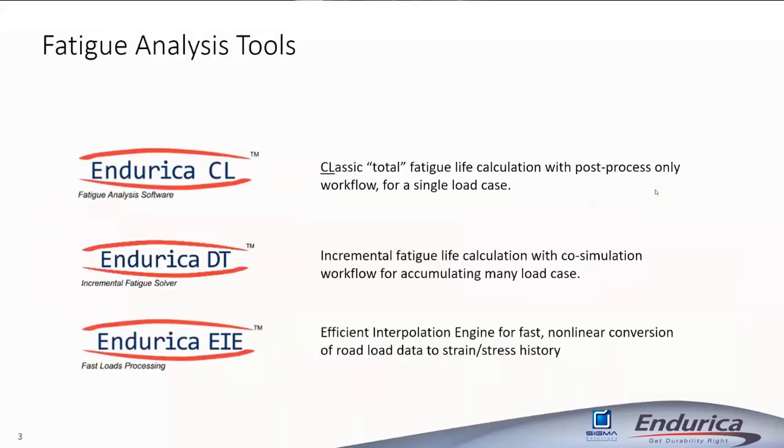We have 3 fatigue solvers, and each of them is focused on a slightly different task or a slightly different workflow. So let me introduce these solvers, and then in my talk, I'm going to give you examples of how each of these can be applied to solve different types of analysis objectives. The first solver, Endurica CL, is our original solver, and in some ways it's the simplest workflow.